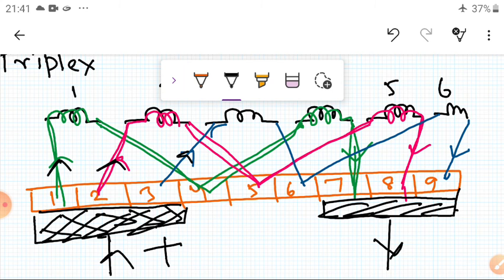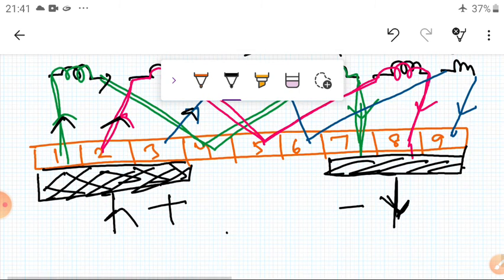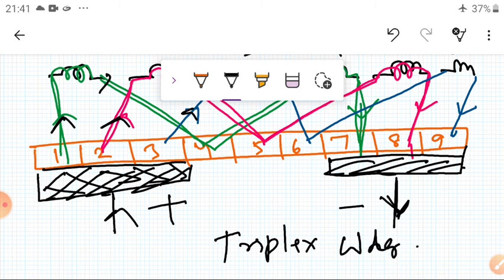Okay, for example, this is positive, this is negative. So such a parallel path, 3 simplex lap windings are in parallel connection. So whatever the current induced is collected here. Okay, so this type of winding is known as the triplex winding. Okay, triplex winding. Okay, this is a basic idea, no need to bother about it. Simply we have the single layer and double layer windings. Okay, so these are the basic ideas and terminology regarding our winding.